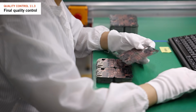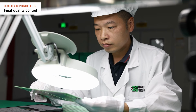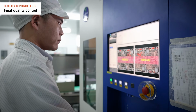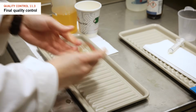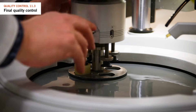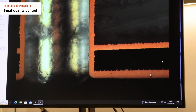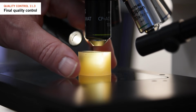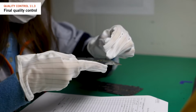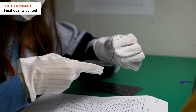The previous inspection steps mainly focus on the appearance, but visual checks can't confirm if the right build is achieved or if the correct copper thickness and ENIG deposit reliability are met. This is why many factories use additional tests like microsections. Microsections help verify builds, inspect copper thicknesses, and identify issues with copper plating and hole wall quality. We also check hole sizes and dimensions to ensure that they match the customer's drawing and specification.